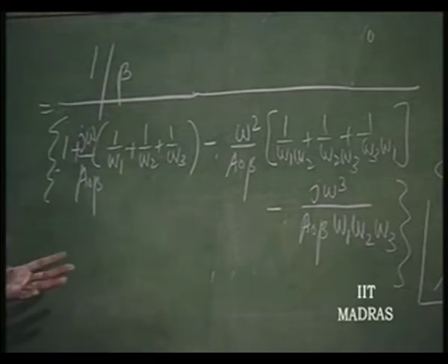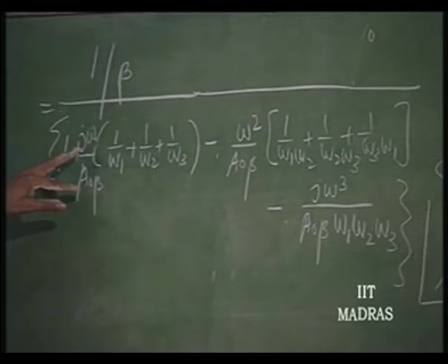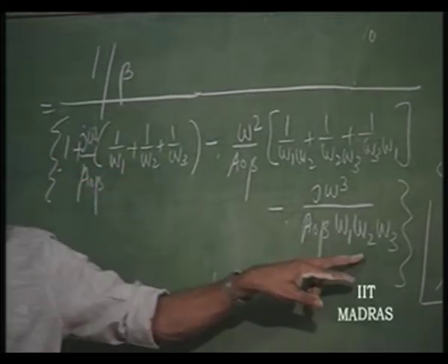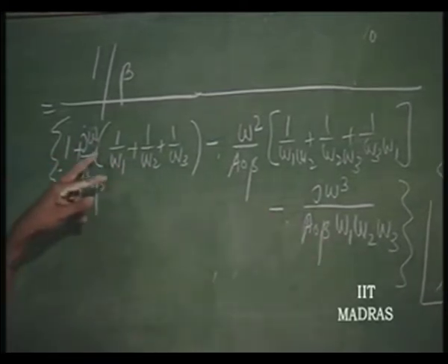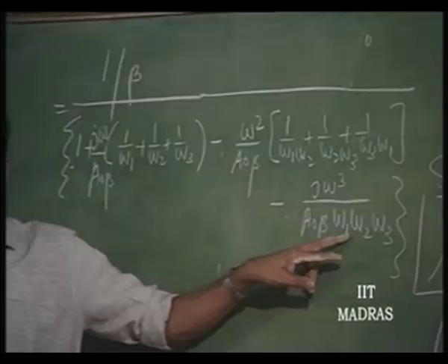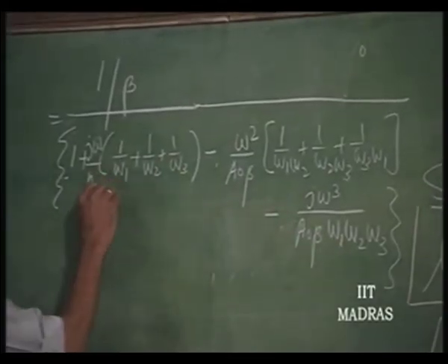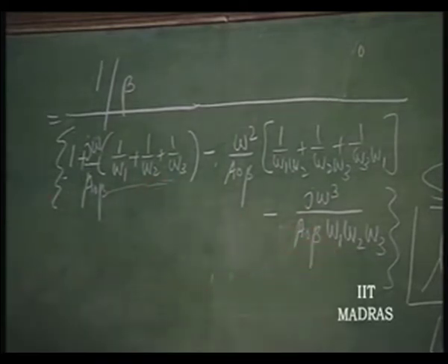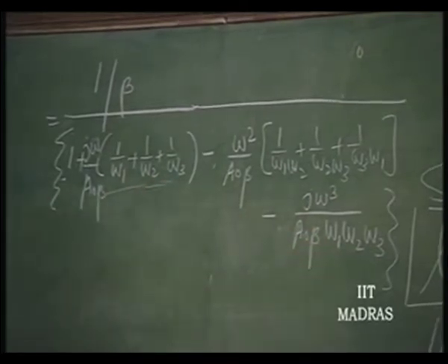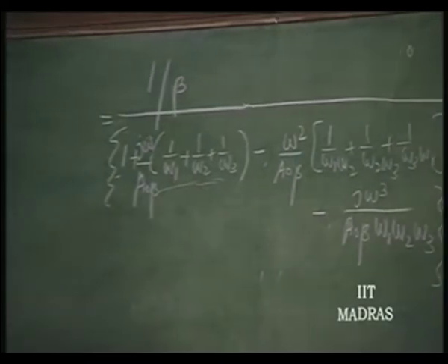Then what happens if it has a phase shift of 180 degrees? Then it becomes purely real. When does it become purely real? When the imaginary part goes to 0. So, you can now find out the frequency at which this becomes purely real. You can see here this becomes equal to this, that is the frequency at which phase shift becomes equal to 180 degrees.